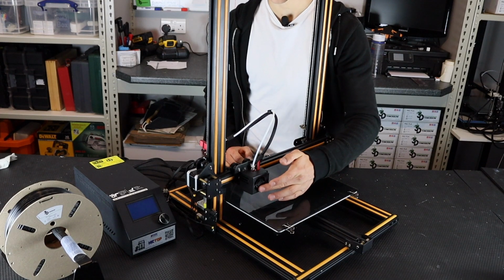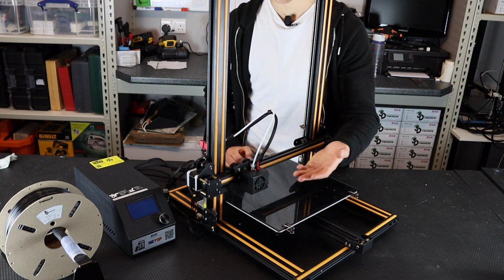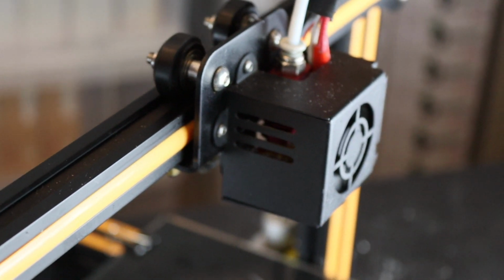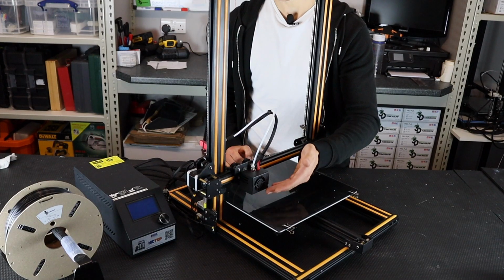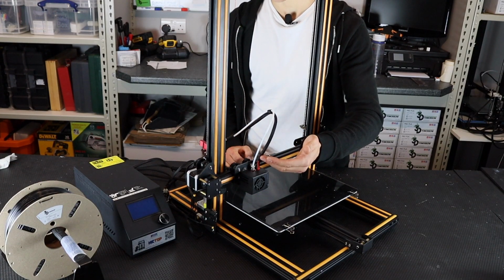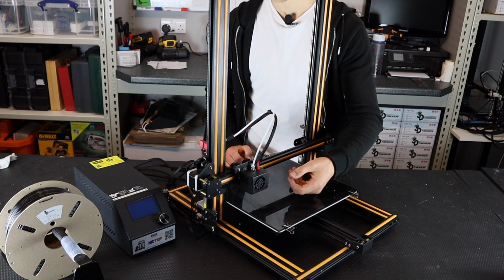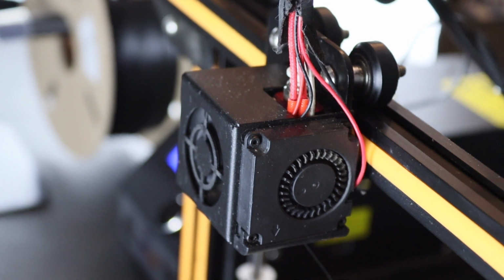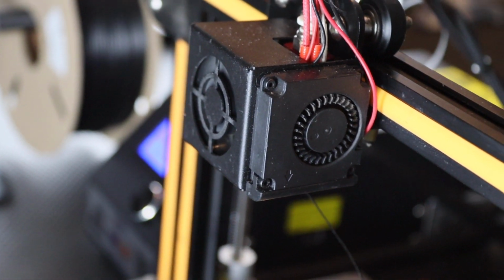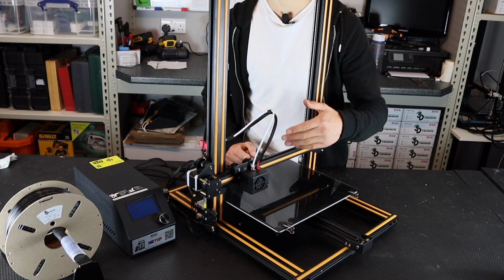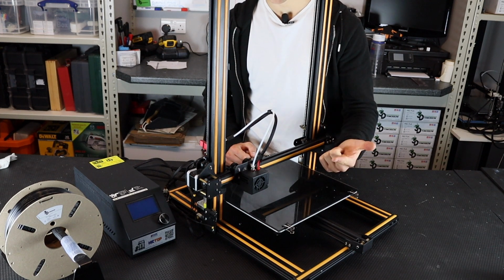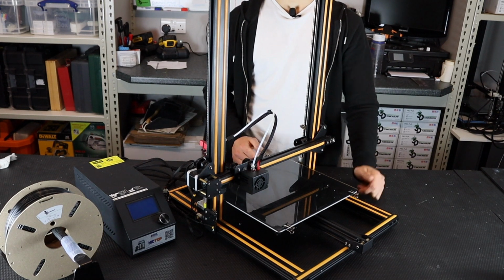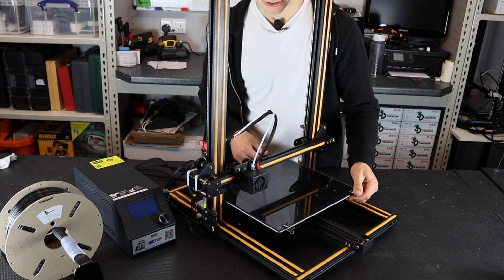This hot end cooling fan at the top ensures that there is a control between where the plastic is molten and is going to be pushed out at the end of the nozzle, and when the plastic is cold and can be pushed normally. The part cooling fan on the side controls how quickly the plastic cools, and controlling this is really vital from everything to part detail, part strength, and also warping prevention, since some materials you can't have this on.